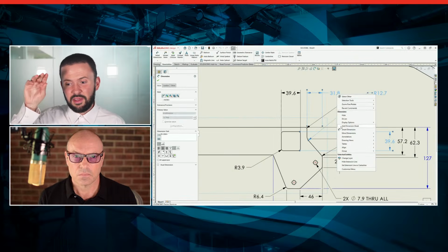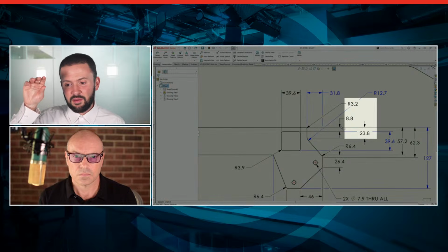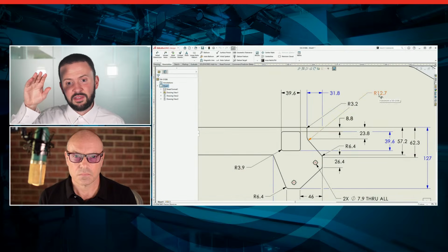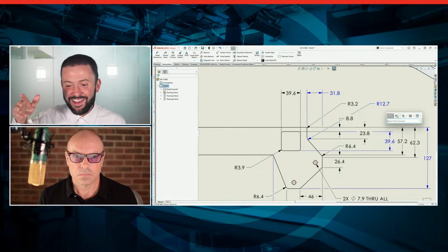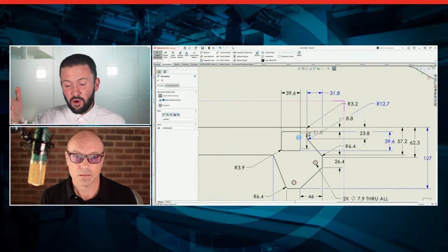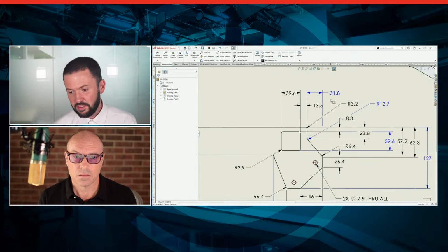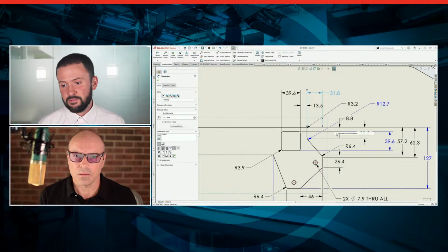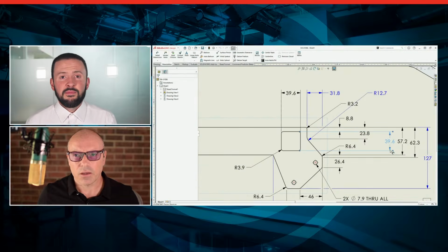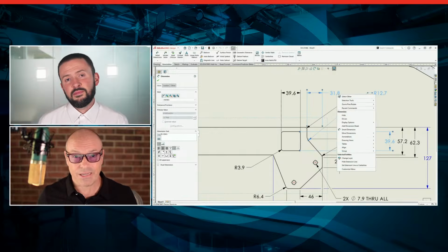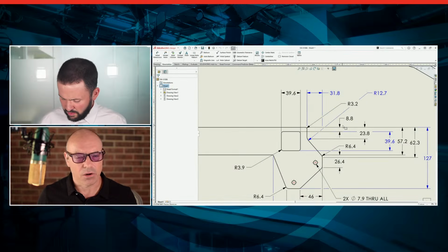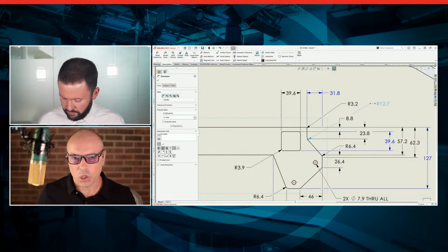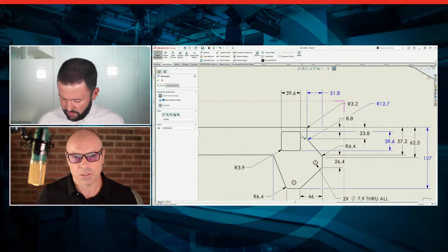And so I think having that ability to break up the extension lines definitely benefits the virtual viewing experience, but also the print one, because the print one can be more unclear, if that makes sense. Yeah, and as I was researching this feature, I couldn't find any specific drawing standard that dictates this. I think it's more a matter of convenience and a desire to make drawings that look as clean and as readable as possible.